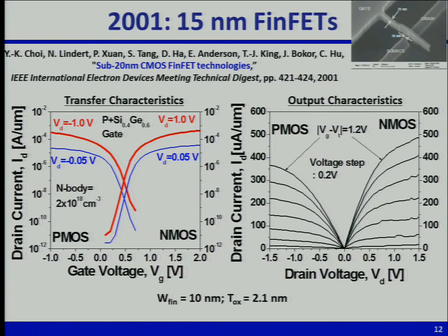Ordinarily, from, let's say, people who take EE131 and so on, what is typically the ratio of the N-channel MOSFET current to the P-channel MOSFET current? 3 or 2 to 1, right? And usually the electron mobility, field effect mobility, is at least 2 times higher than the hole field effect mobility.